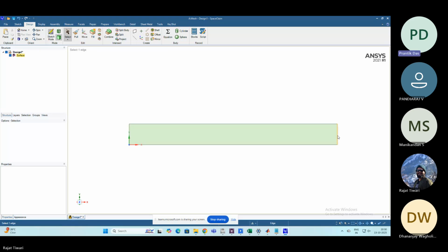What we are going to do is simulate the pipe flow, the flow of water through the domain. This is a 2D problem, which we are going to solve by using the SIMPLE algorithm. Is it clear to all of you? At the wall, we are going to impose a no-slip boundary condition. This one is a rectangular slab, by the way. Is it clear to all of you? Yes, sir.